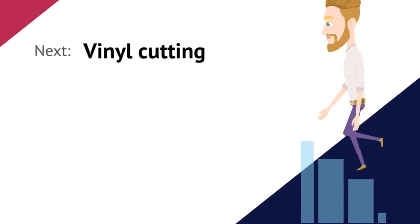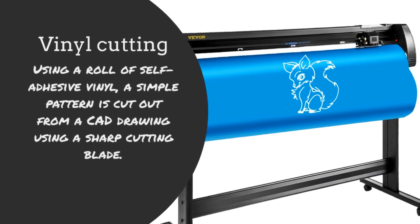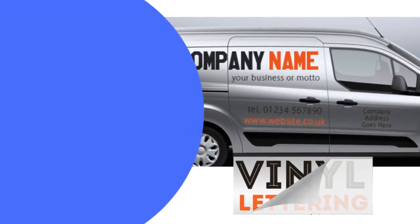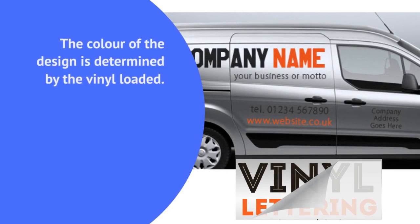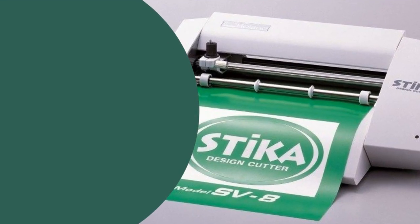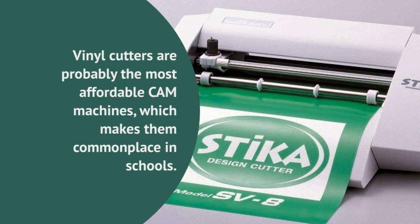Next, vinyl cutting. Using a roll of self-adhesive vinyl, a simple pattern is cut out from a CAD drawing using a sharp cutting blade. The colour of the design is determined by the vinyl loaded. This process is used to produce lettering or shapes, for sign writing, or for applying branding to vehicles. Vinyl cutters are probably the most affordable CAM machines, which makes them commonplace in schools.